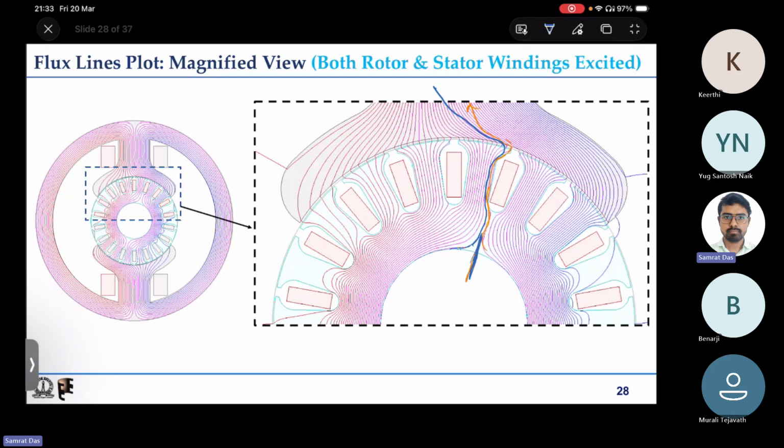And why is the angle so low compared to the vertical angle? You can also explain it through, say, vector addition. So you have a very strong magnetic flux density vector due to field, say BF, and you have a quite weak flux density vector due to armature, and in space both these vectors actually get added up. So if you do vector addition, you get the